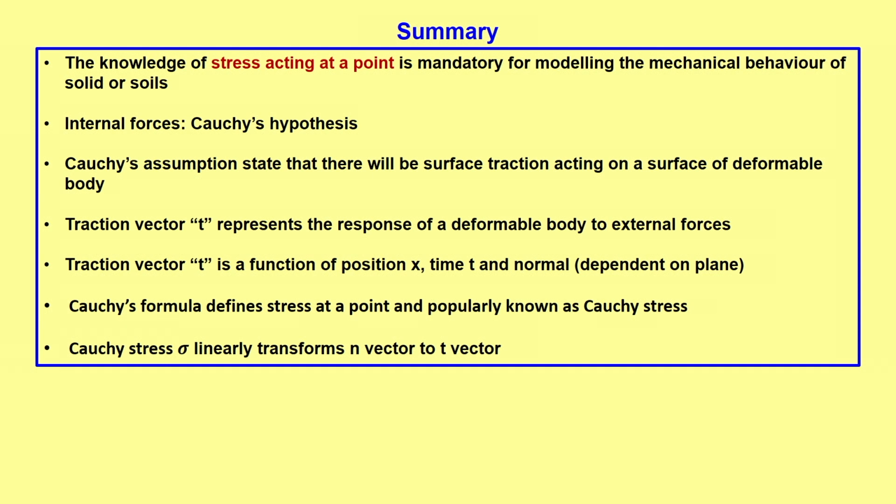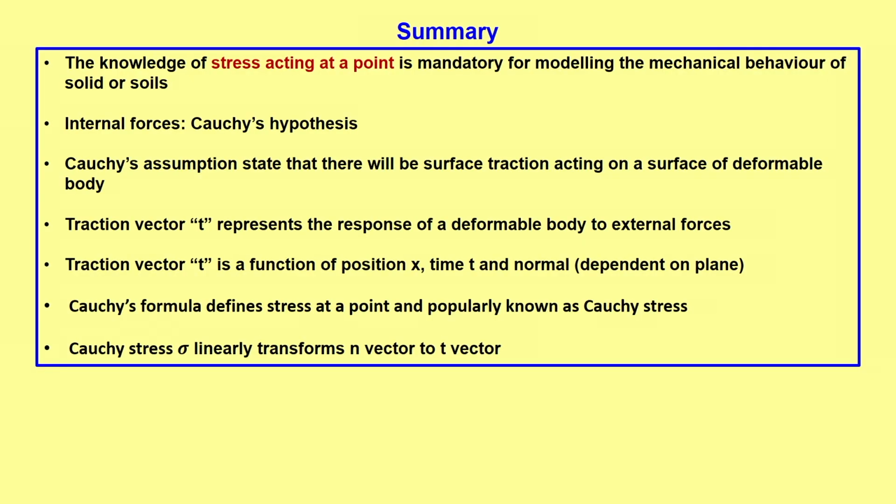So, in summary, the knowledge of stress acting at a point is mandatory for modeling the mechanical behavior of solids or soils. In our case, it is advanced soil mechanics, so that is why I have specified the term soils as well. Internal forces are entirely dependent on Cauchy's hypothesis, which states that there will be a surface traction acting on a surface of a deformable body, and the entire definition of stress acting at a point is dependent on this.